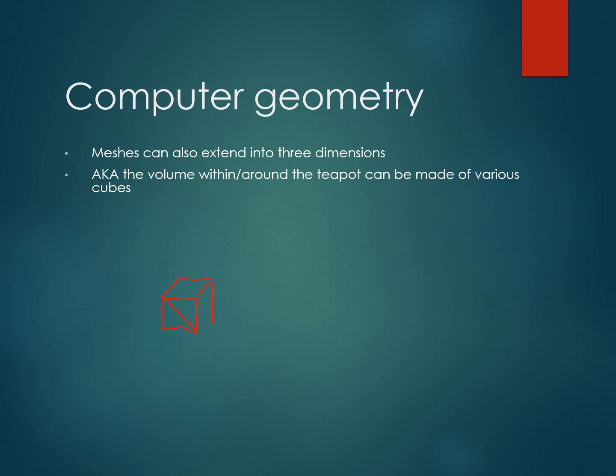So we effectively turn these into cubes, and these cubes then form the basis of our cells, is what we call them in the simulation, where each volume element will have temperature and pressure and velocity data associated with it. And we build out these surface two-dimensional files. We fill them with a bunch of these 3D cubes, and that becomes the starting point for our simulations.